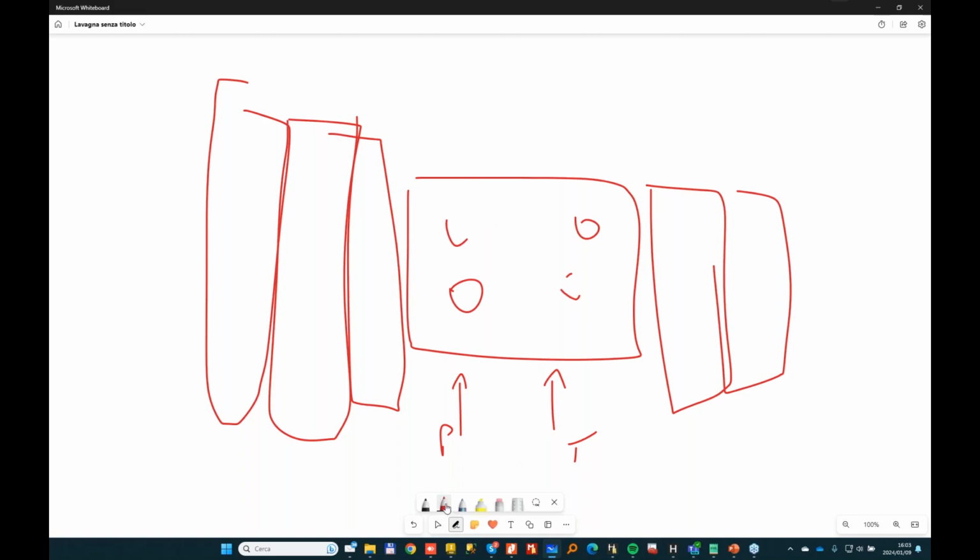Some considerations normally when we do this kind of exercise. If I look frontally at this block, with the working section here, we want to limit the height of the element not to go below the element of the working section, because usually we have end plates on both sides, so we really want to fix the assembly on the bottom part. So my constraint will be that the bottom part of my custom inlet will be almost on the same line as the working section. So here I will have my P and T port.